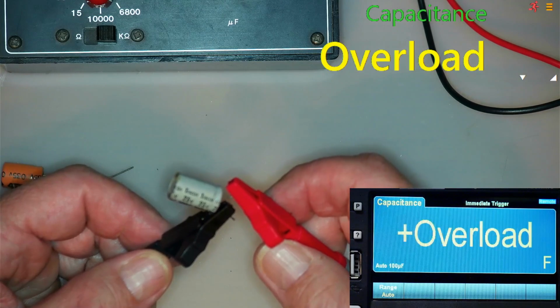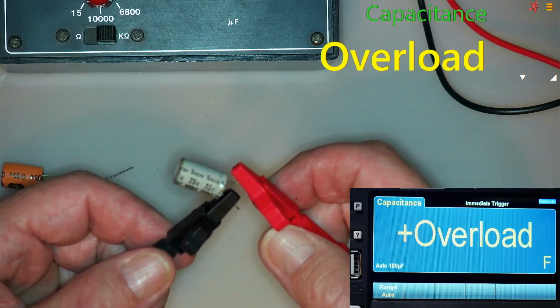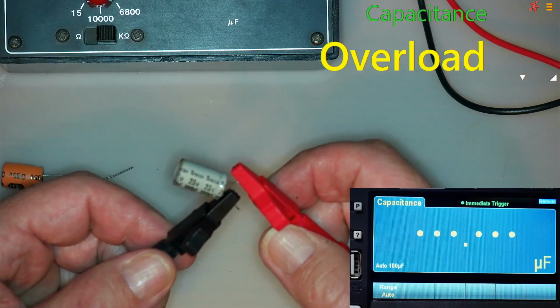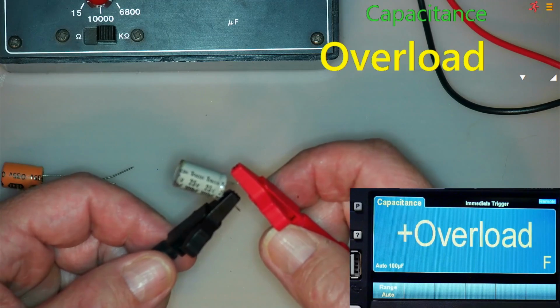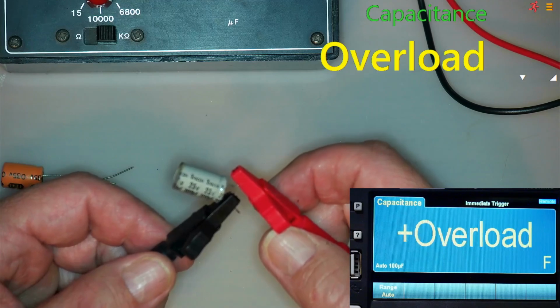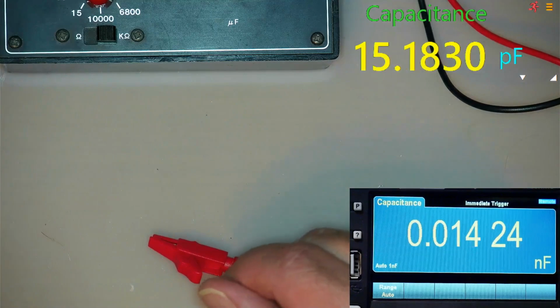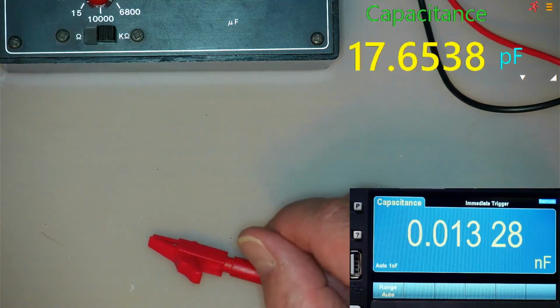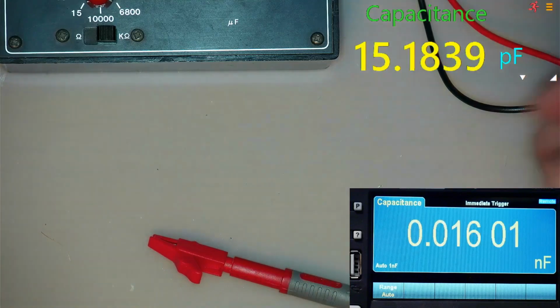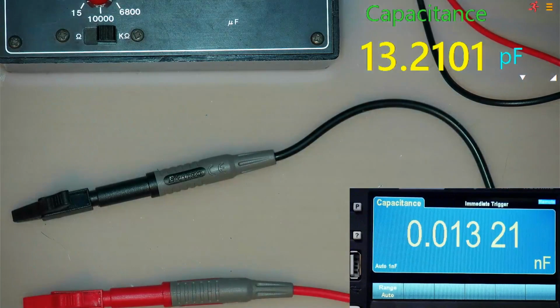I don't think this one is more than 120, and it's just not able to deal with that. As you can see, the highest range it's got is the 100 microfarad range. Yeah, can't read this one. So that's the capacitance reading on this multimeter, and I presume the Keysight one would be the same, since this is what they cloned and copied. I'm not sure though, I haven't looked at the specs.